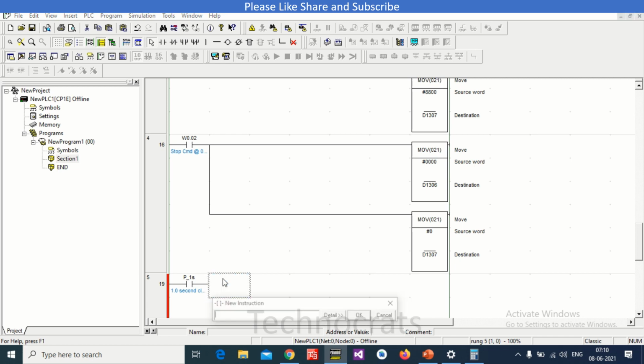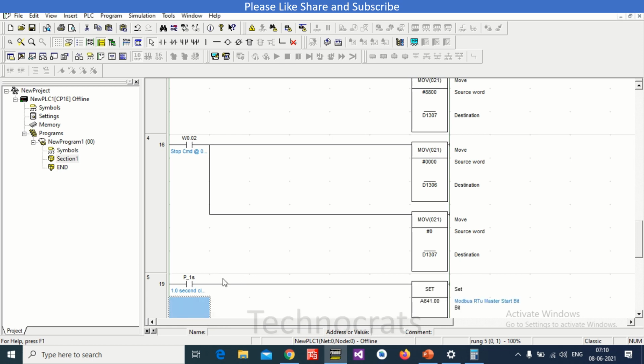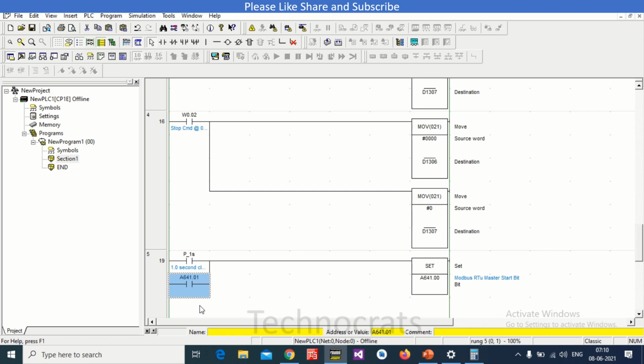Set the bit A641.0, that is your Modbus RTU master start bit, or you can also set it by A641.01, this is your master execution normal flag.